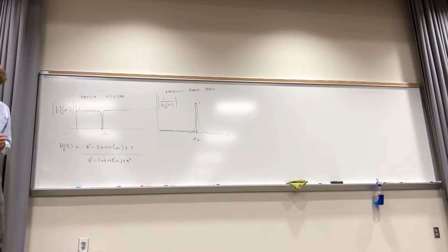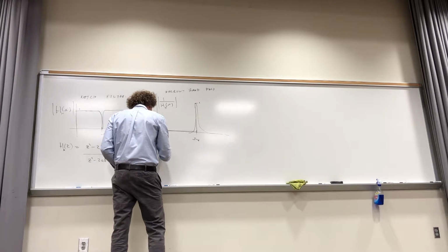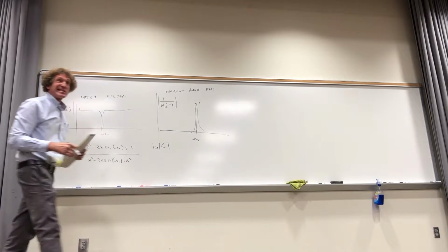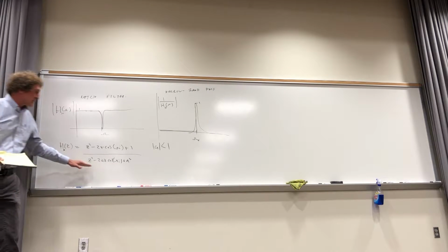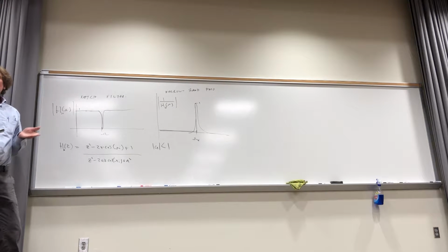And that would give you it. Now a, for the notch filter, magnitude of a is less than 1, or else you basically just get everything passing. But the reason you have this lower part, the denominator, is so other frequencies aren't adversely affected. That's the reason it's there. Everybody got that? That's the reason.